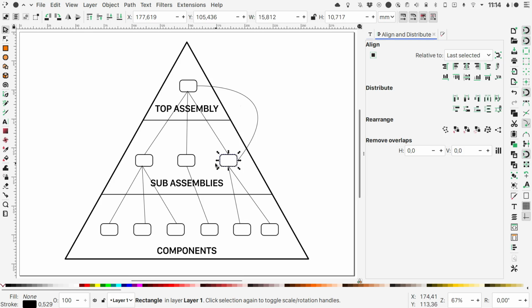What we can do is to create our reference horizontally. We can reference the geometry in one of the subassemblies that will later go on to build our top assembly. So bear in mind that the geometry that we wanted to reference in the top assembly is present in one of the subassemblies. To avoid the cyclic reference problem when modeling, always avoid referencing top assembly geometry, but go horizontally, referencing the geometry in the subassemblies that will form the top assembly.